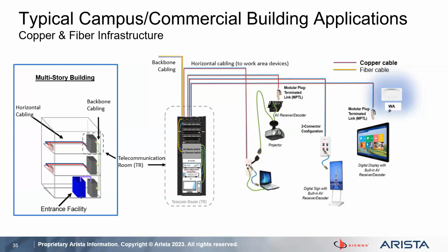So typically from a cabling standpoint, you could see here highlighted, you're running fiber cabling as the backbone between floors typically. And then the horizontal cabling is typically copper. For most of these applications now, we're seeing category 6A as pretty much the standard go-to for WAPs, as well as all the other applications to handle the bandwidth that's out there. So pretty common that we're seeing today.